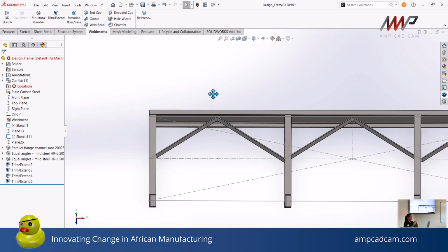So instead of welding everything together, which I can do, I'm going to bolt these things together so that it has the ability to, one, easily be removed if necessary, and two, that it has a little bit of leeway so that it doesn't just snap off at the first bump it hits.